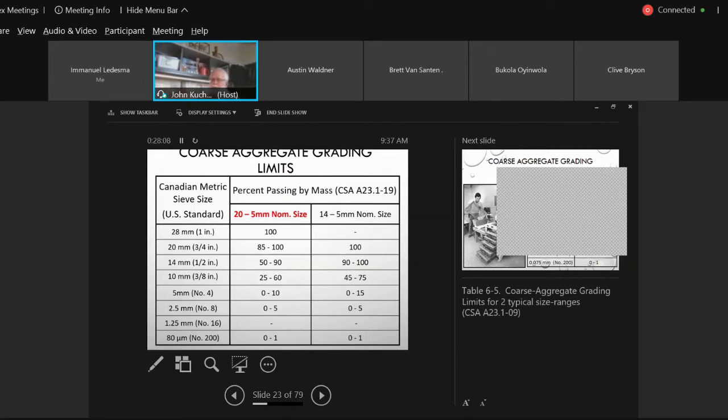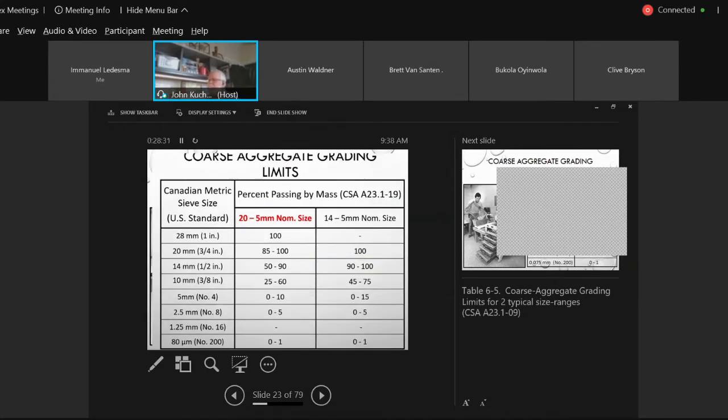So you may have to go to a smaller size aggregate. So now the maximum nominal size is 14, which is approximately a half inch, okay? 3/4, half inch. So here you can see now that it's a lot finer because the top size is finer. So applications vary. What is that concrete going to be used for?